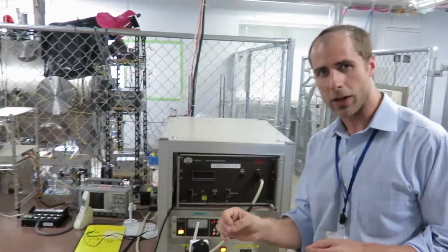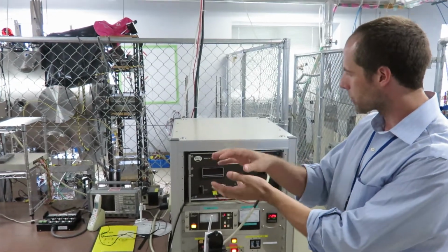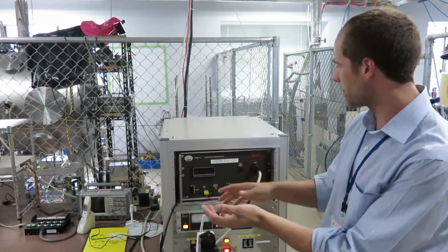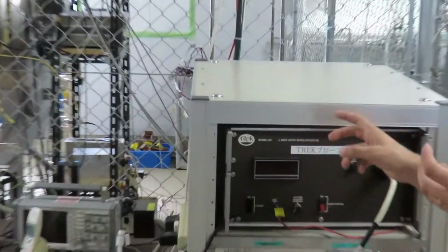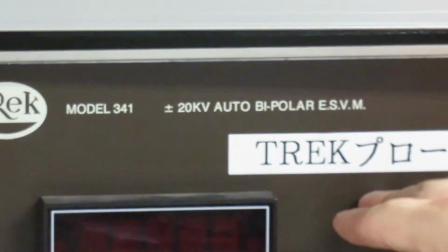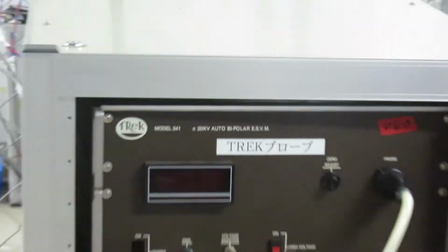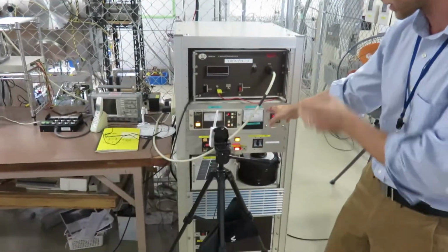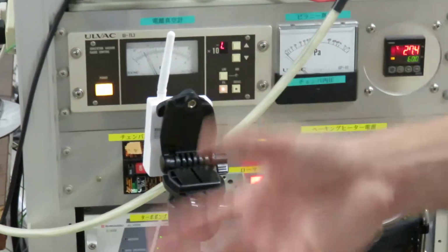There's the probe itself, which has a vibrating head that approaches the potential of the object that it's close to, but the underlying principle is to use an electrostatic voltmeter, an ESVM, to achieve that. So this is the ESVM, and the probe itself is inside the chamber, close to the sample. And the rest of this is a control panel for the chamber, operating the pumps. We get a readout on the pressure, etc.